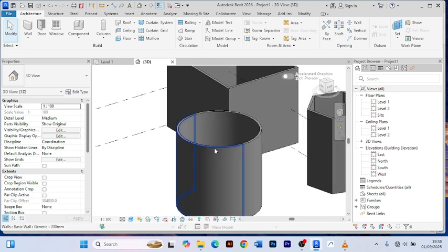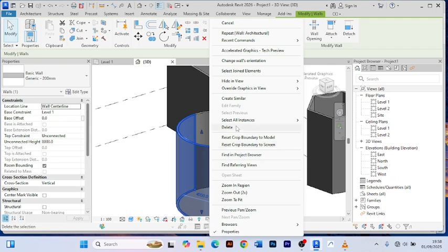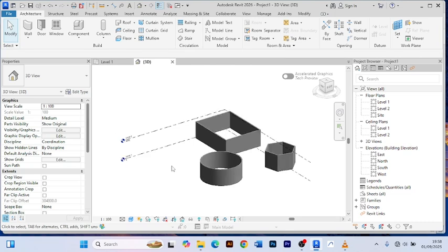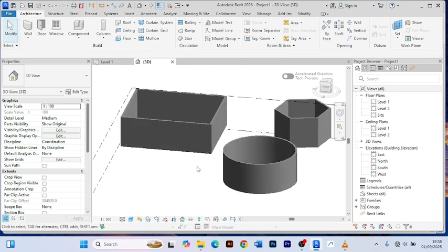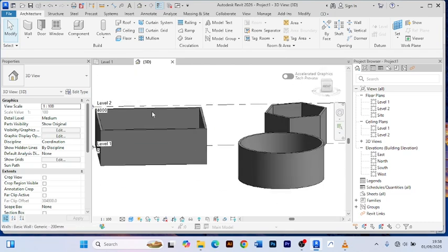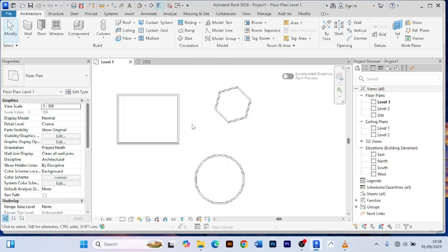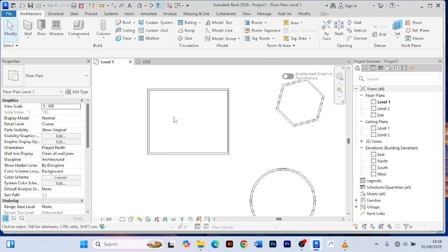I'm going to change their height. These are all tall. I'll select all instances in the entire project. Then I'll reduce their height to 3.5 meters, just like that. So now these are the walls that we have. We can now create slabs or the floors.